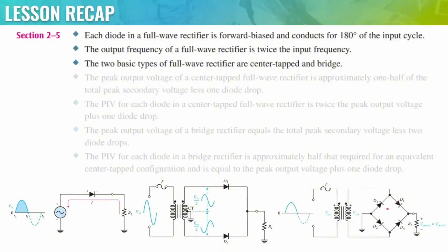For the bridge type full wave rectifier, it has four diodes, and usually two of them are on and two of them are off. As we can see here, there you have an alternating current. For this branch, it's going to pass through this diode and get blocked by the reverse diode. Similarly, we're going to pass through this diode, and then this one is going to get blocked.